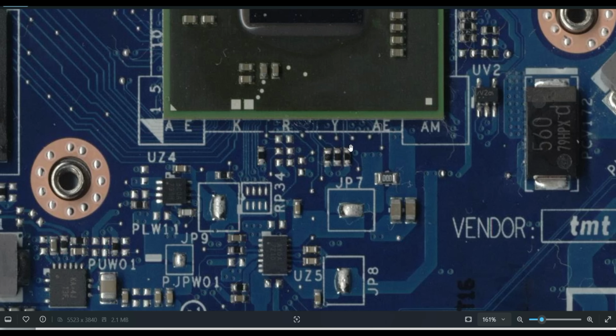In case an intermediate voltage is there, then you need to replace this resistor, or this IC may be faulty. There should not be an intermediate voltage. Intermediate means, for example, here is a 10K resistor, here is 3 volts, and here you will get 2.8 volts or 2.9 volts, or maybe 0. It should not be 1 or 1.5, because it depends on the IC. If the IC is driving it, then it's okay.